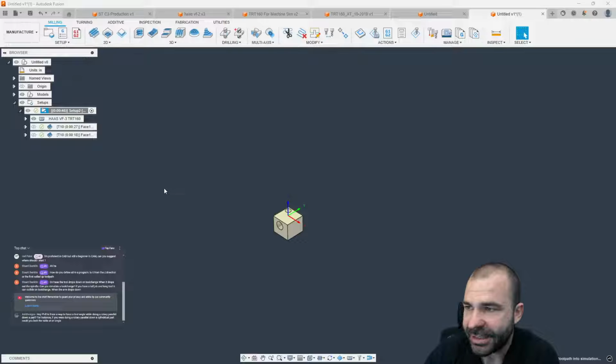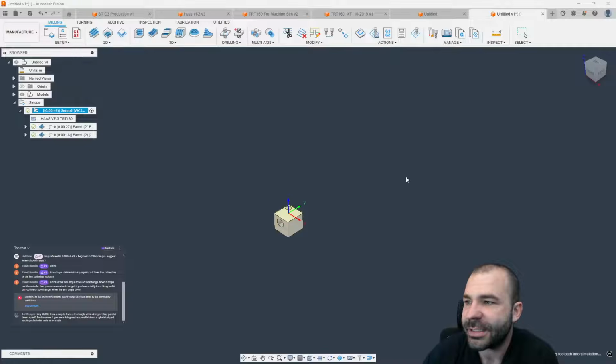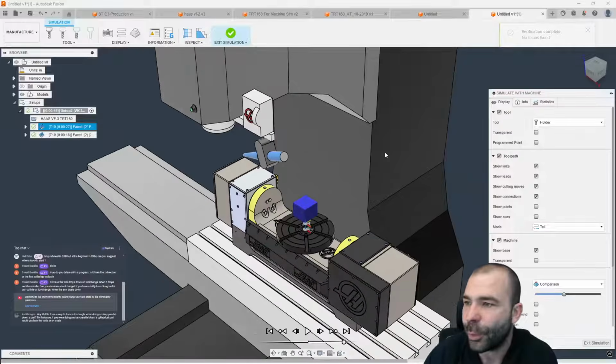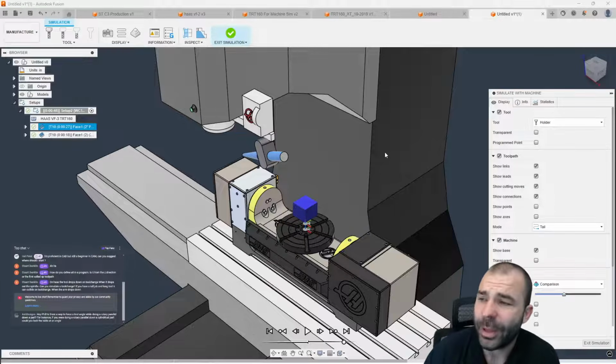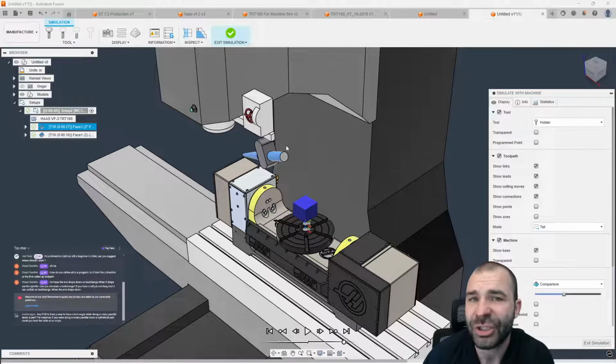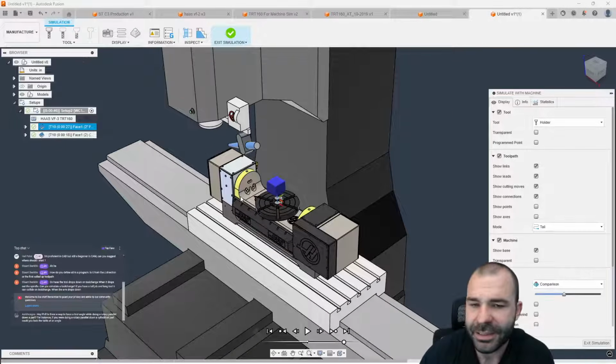Ash Design, great to see you out there, buddy. Is there a way to force a tool angle while doing a rotary parallel down a part? For instance, we are doing a rotary parallel down a cylinder to just lock the table at an angle. So the question, I guess, would be, Ash, that's something I can answer this Friday by all means. But if you're looking to do something in 3-axis only, you need to utilize tool orientation. However, if you're looking to fix a 20-degree angle based on that tool against the surface, that's something where we're going to need to look at some other toolpath.